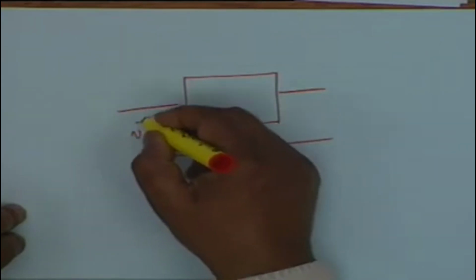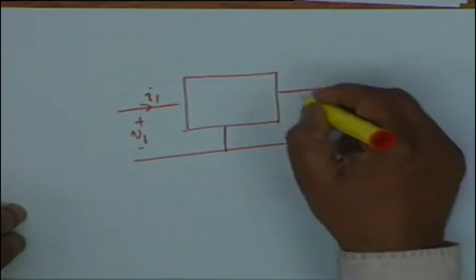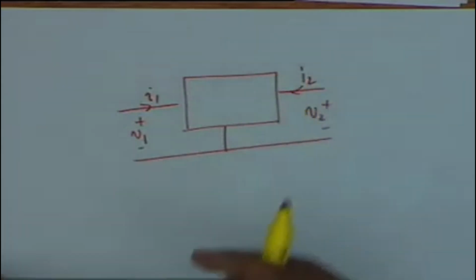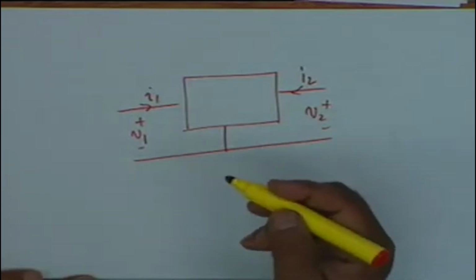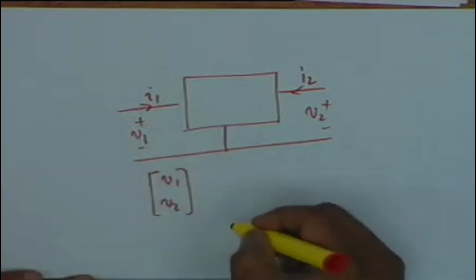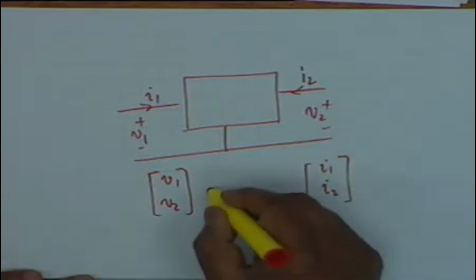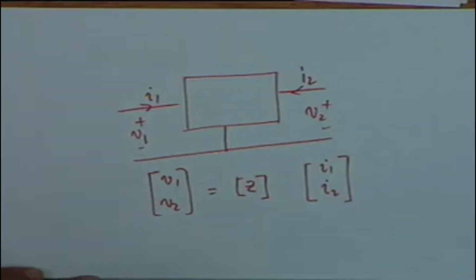Okay. If we do that, then any 2-port device which has 3 terminals, we say this is V1, I1 in general, and V2, I2. We always use currents going in, and these can be characterized in 6 different ways. If we take V1 and V2 as dependent variables and I1 and I2 as independent variables, then the parameters are the so-called Z parameters or open circuit impedance parameters.